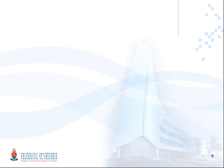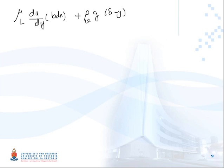Okay, now let's write it on the next page and see if we can get to the correlation suggested by Nusselt. It's very interesting and nice. The viscous force mu du/dy b dx plus the buoyancy force is equal to rho L g b dx.